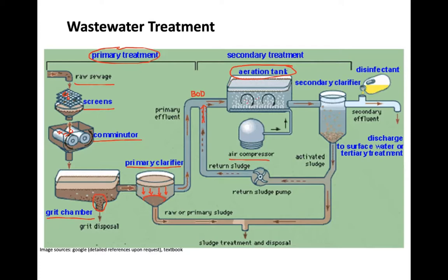So as it says in the video, you can think of this process as, let's say, the happy bacteria that can have an unlimited amount of food, right? Because we have a high concentration of the organics. So we have the bacteria, even if they're in small amounts, they can quickly populate themselves, right? To increase their number into a very large population. And then we can efficiently reduce the concentration of the organics. And basically after the BOD is reduced, right?